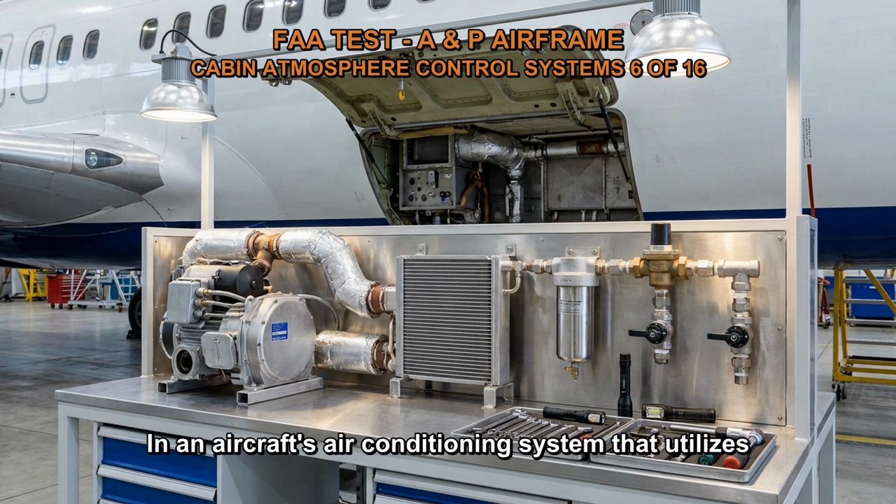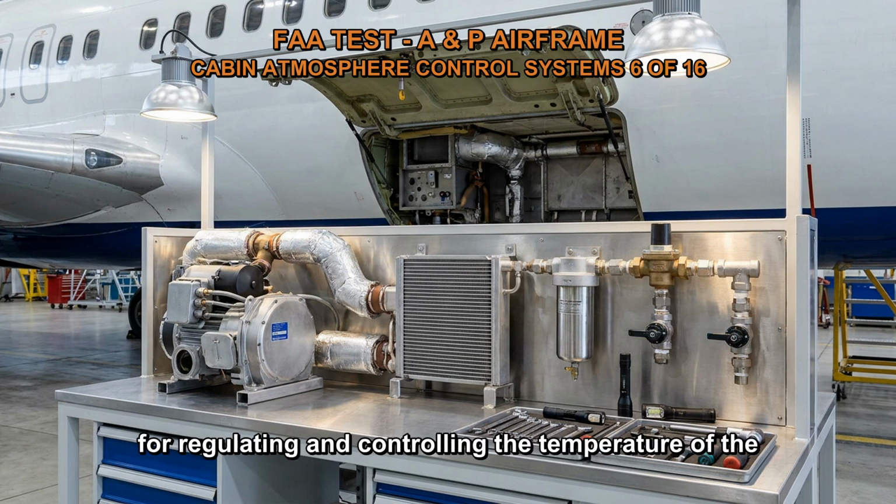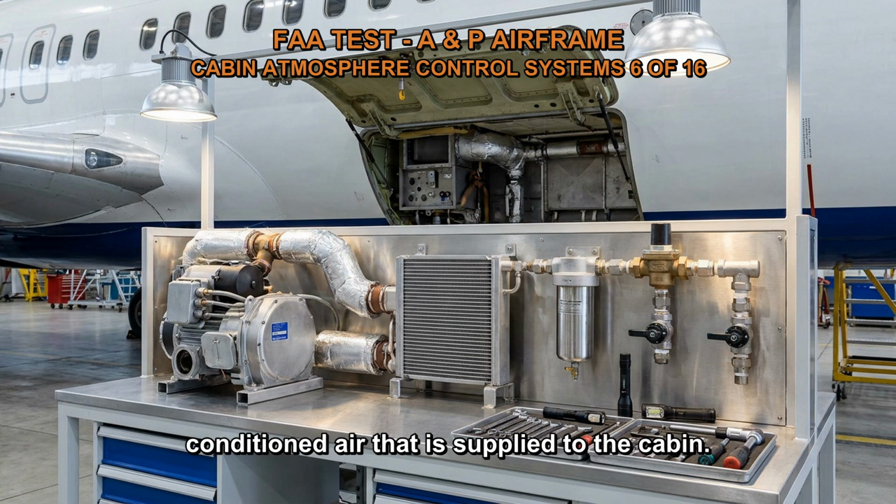In an aircraft's air conditioning system that utilizes compressor bleed air, the mixing valve is responsible for regulating and controlling the temperature of the conditioned air that is supplied to the cabin. It allows for a precise blend of hot air, cool air, and cold air to achieve the desired cabin temperature. The mixing valve receives the hot compressed air from the aircraft's engine bleed air system. This hot air is then mixed with cooler air to achieve the desired temperature.